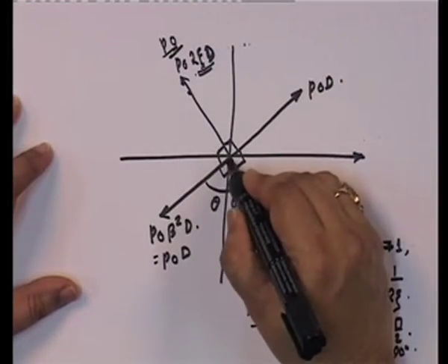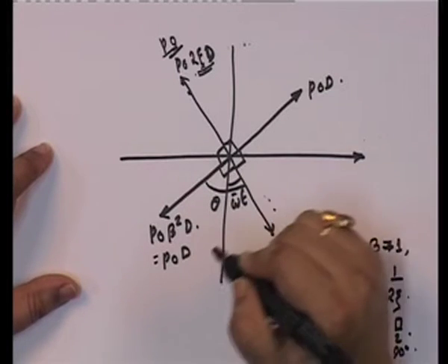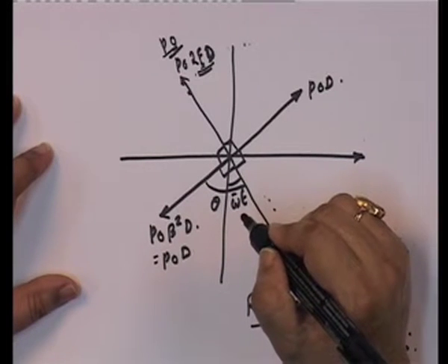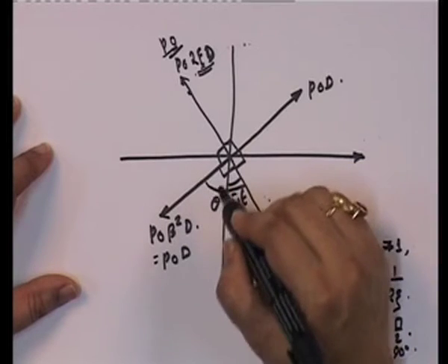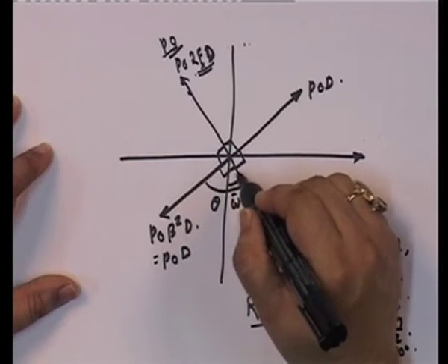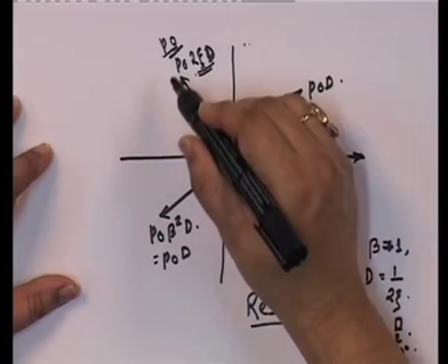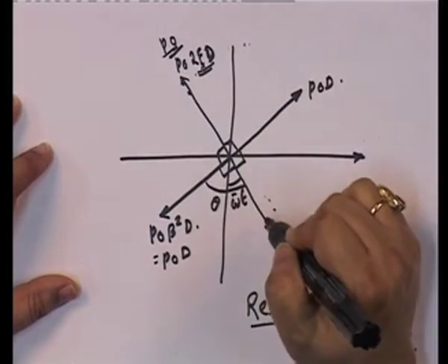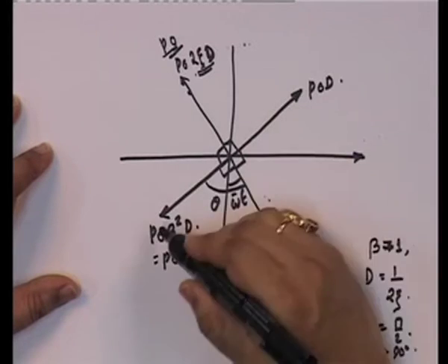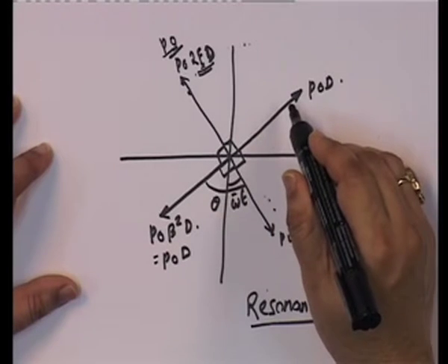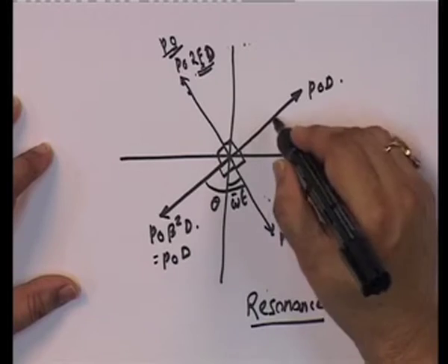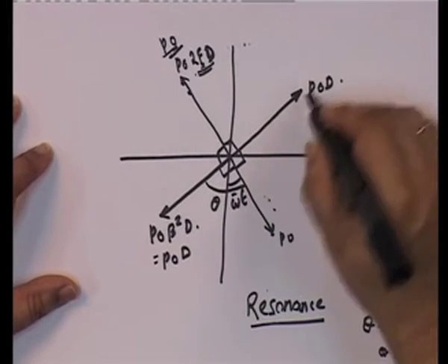And look at the inertial force and the elastic force, they are completely out of phase, sorry, they are 90 degrees out of phase with the applied load and the damping force, and they balance each other out. Note that these values will be very large because P naught d is very large.